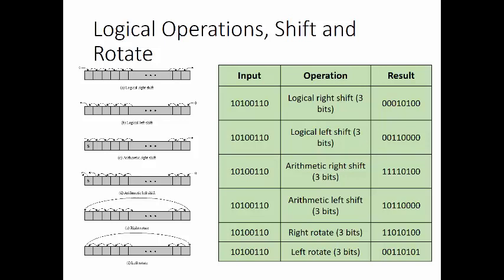The NOT operation obviously inverts a bit, and OR and the exclusive OR are the most common logical functions with two operands, and equal is useful as a binary test. A really cool trick to get ones complement is to exclusive OR a word with another one set to all ones, and that will give you ones complement.